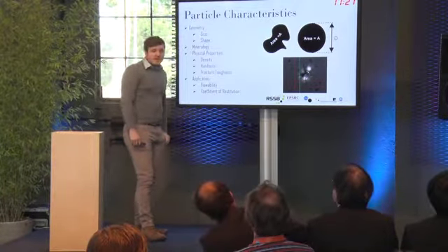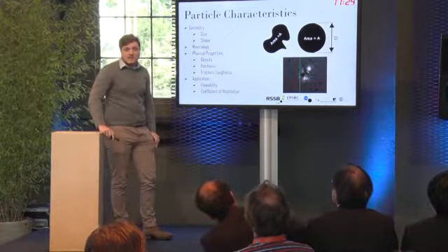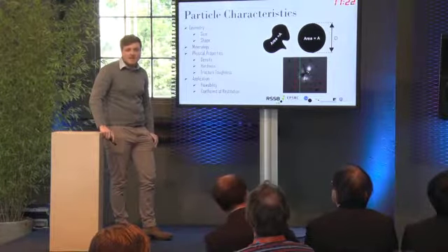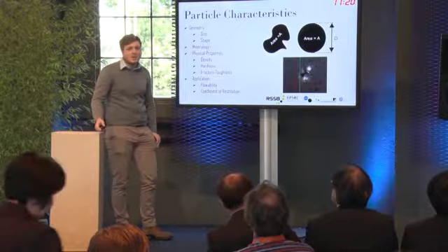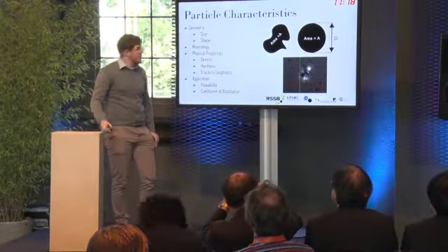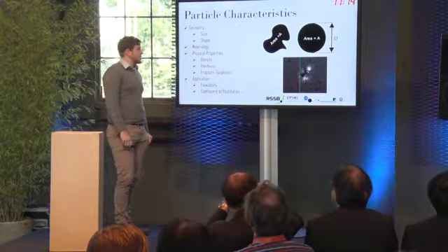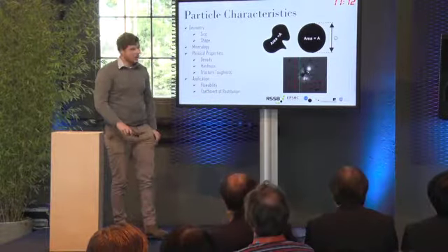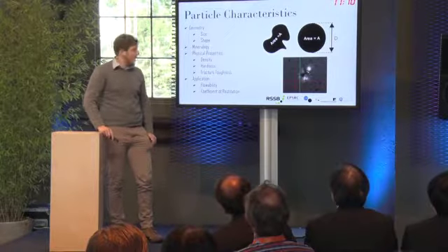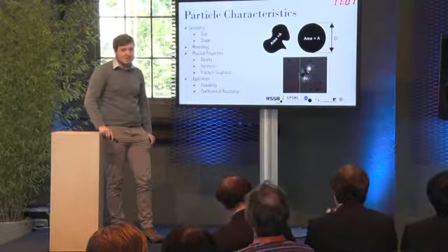So I also looked at mineralogy, which is quite simply looking through an XRD and then trying to find what sort of mineral content is in there, for example quartz. And then physical properties also went into a little bit. So I looked at density using a water displacement method.